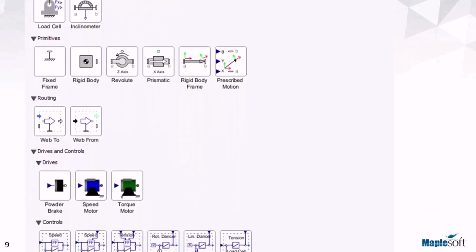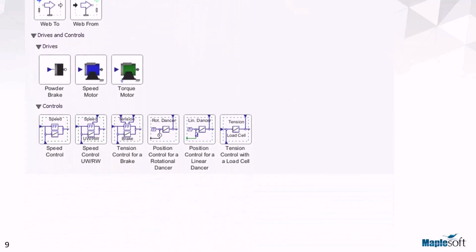The library includes groups of subcomponents for spans, for rollers or nip rollers, source and sink, or wind and unwind, one web or multiple webs, components to allow you to merge multiple webs together, a component to allow you to split a web into parallel strips, additional utility components to move things around or connect things together, and drives, electrical motors, and controllers to create feedback loops and create a complete system.